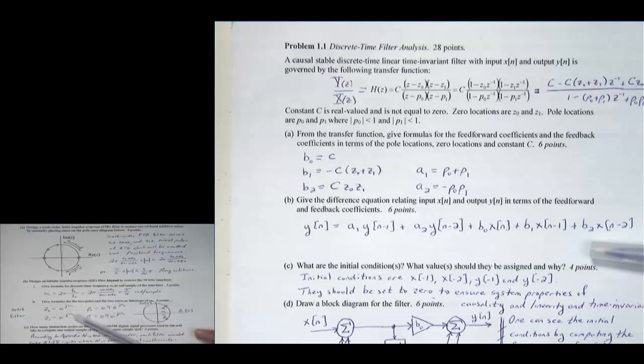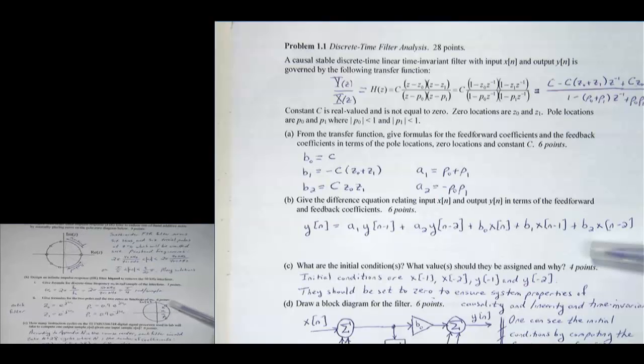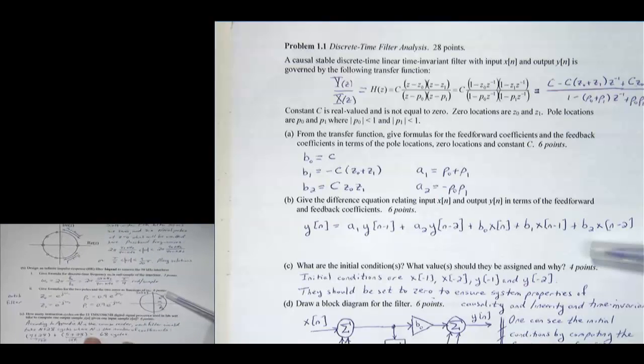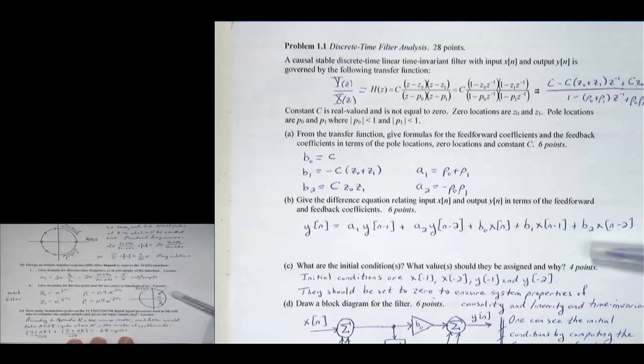The zero locations should be on the unit circle at the angle omega naught, and then the pole should be slightly off the unit circle, slightly inside the unit circle at the same angle. We have our notch filter at omega naught. You did great on this one. I've asked lots of notch filter questions in the past. It's one of my favorite questions. I will tell you these are really hard to get right in fixed point arithmetic. Not that you have to worry about that in lab because it's floating point, but you need a lot of extra precision to get this right in fixed point. They're painful to implement. Yes?